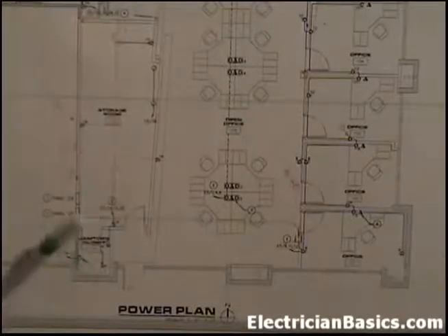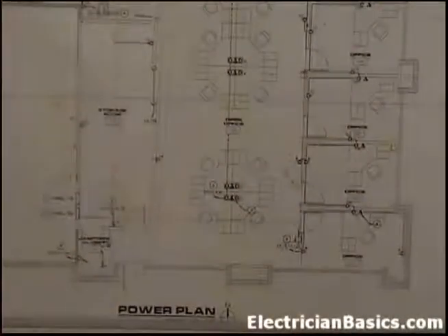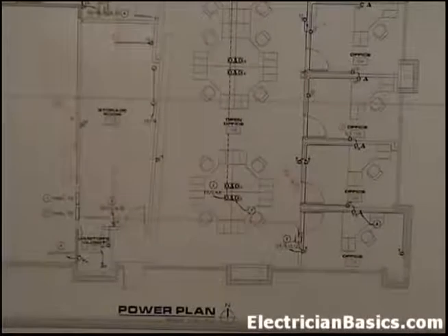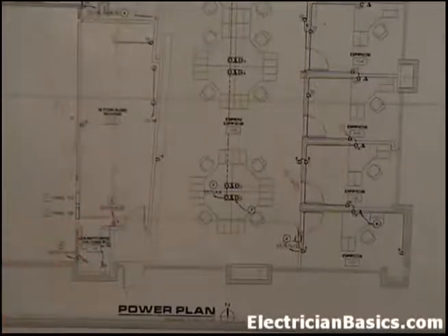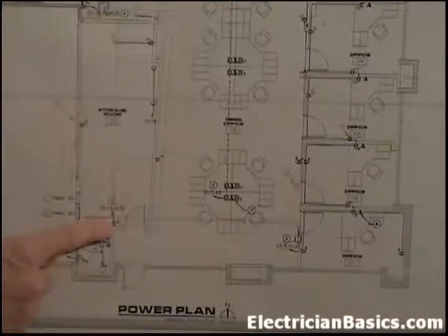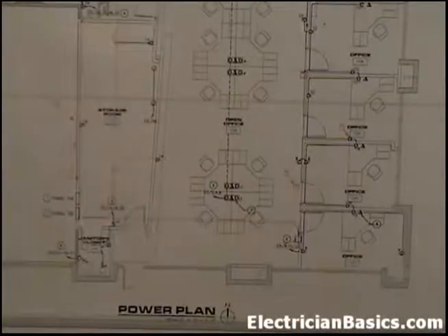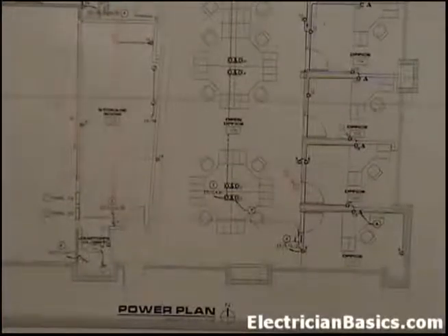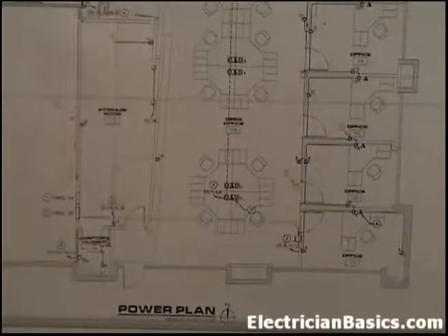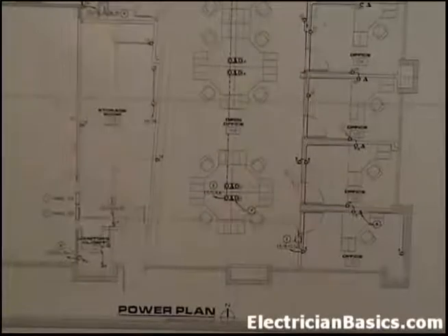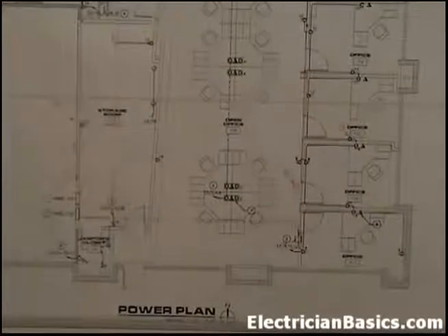Another tool we're going to use is this whiteout marker. Let me show you how we use that. We're down here, see this circuit 14, and this is home run E5, 14, 16, 18. On the plan, it had it here and it says go home with it. On our red line drawings, we're going to show the conduit sometimes. It depends on your style of red line drawing. If you can get a straight line with an arrow to the panel, that's good enough too. There's really no set style. They just must be understandable.